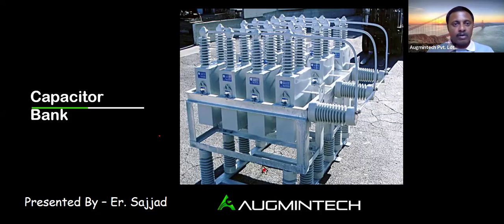So if I'm not using any capacitor banks, that 20 kVAR, kilovolt ampere reactive, would be supplied by the utility itself. In that case, the system is not efficient. Instead of using 10 kilowatts, you might be using 15 kilowatts. That's the basic thing. So if we are going to install the capacitor banks, maybe up to 15 kVAR I'm compensating. Just 5 kVAR might be supplied by the utility. In that case, okay, fine.